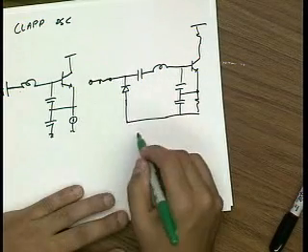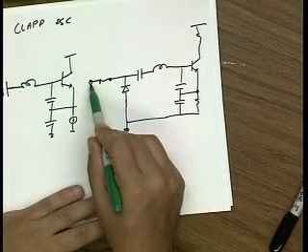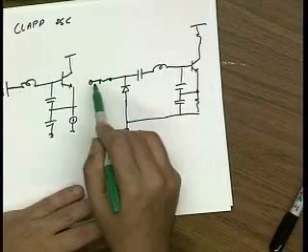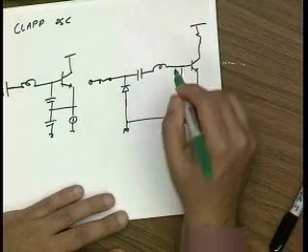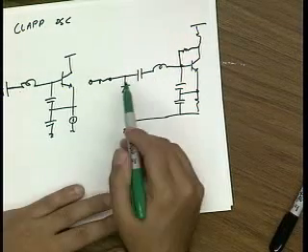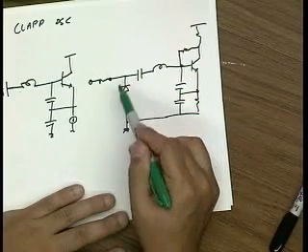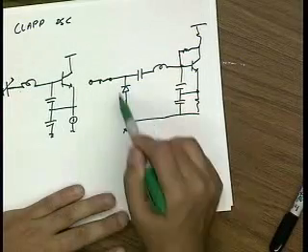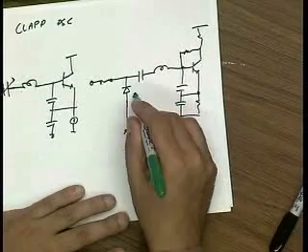Because the DC point here will not disturb this circuit, I can vary this DC value because I have this cap isolation. Maybe I have a large resistor to bias this up. Now I can change this DC value, which will change the capacitance here. So this becomes a variable capacitor, and that will change the resonant frequency of my tank, and so I get a VCO.